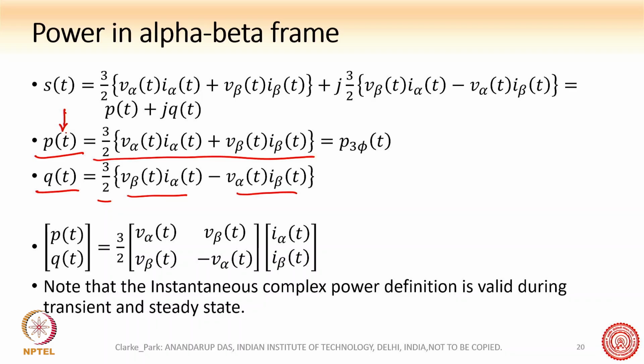This is instantaneous active power and instantaneous reactive power. This is very useful in particular for implementation cases where, suppose you have a DSP and you want to quickly find out what power is flowing in the circuit without having to wait for the whole cycle to complete. And so we will use these quantities, PT and QT, instantaneous active and reactive powers. And so these are the instantaneous complex powers like this.